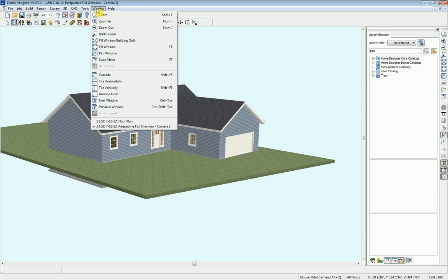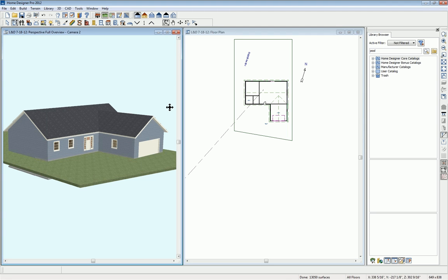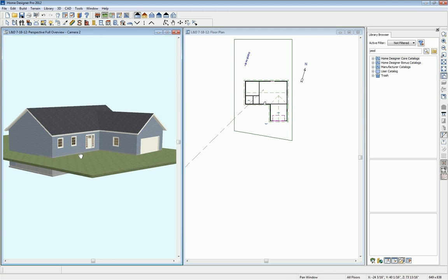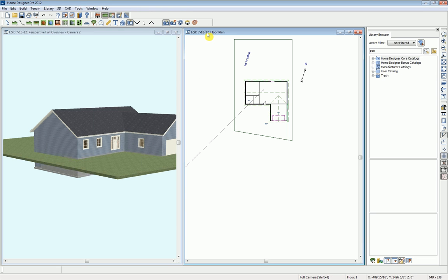And now I'm going to tile this vertically. Under Window, we have Tile Vertically, and you'll also notice different shortcuts. So you can use Shift F6 to tile these as well. So let's get into our terrain elevation tools. Across the top, we'll have our elevation controls, and we have points. So you can just put a single point somewhere. You can get into your elevation lines, spline or curved lines. You can also do regions. And I'm going to do our regions today.